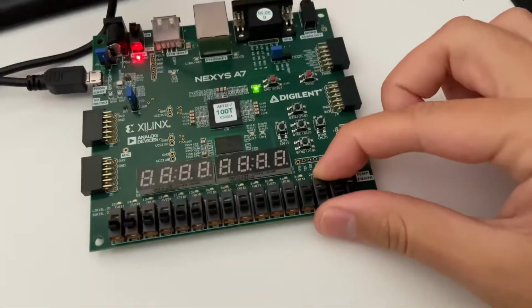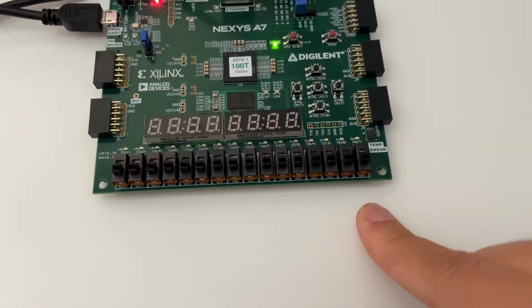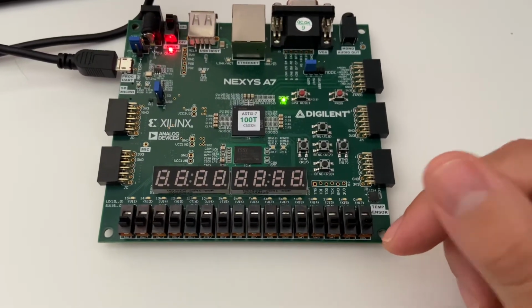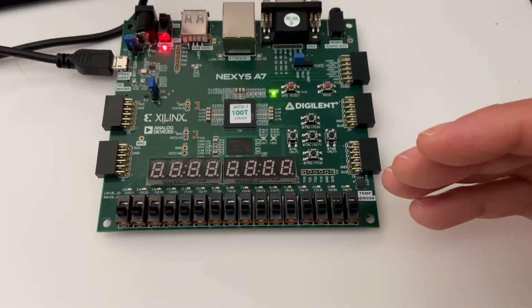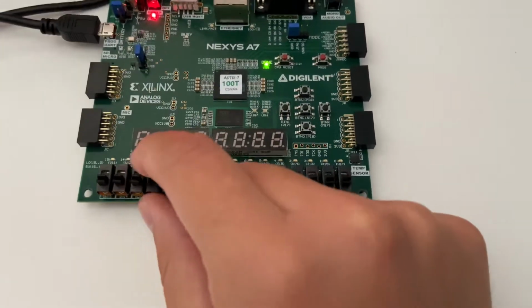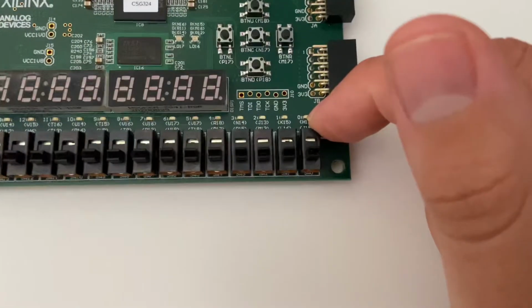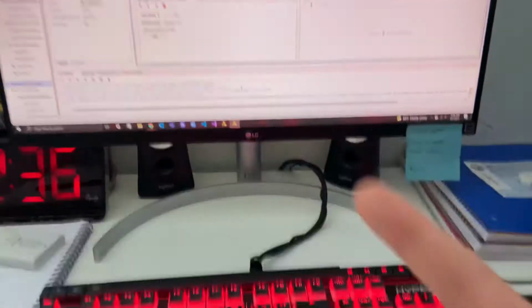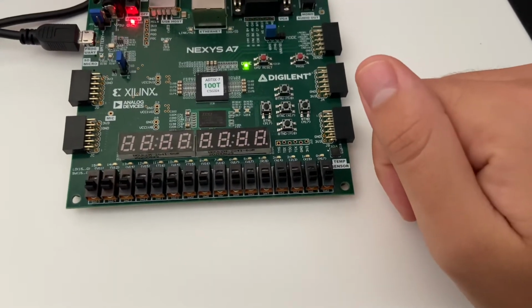Okay, so to start, we have our edge cases right here. Just to avoid any ambiguity, I made it so that the square wave generator only gives an output if M and N are both non-zero values. So if M is 0 and N is 1, still no output. Also vice versa, and if they're both 0, then we're not going to have an output. This LED right here will let us know if there's an output. I can run all the edge cases on here, but I thought it'd be easier to have the LED show us that for a real quick simulation.